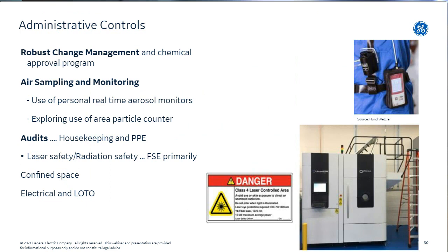Administrative controls that we can do are pretty much, I would say, on 3 areas that you can emphasize. First of all, have a good change management. That means when you're operating your machine and you want to change the material, or you have a new employee operating a machine, or you get a new machine, a larger one, and you have experience from the same manufacturer with a smaller system, do a good change management here. Understand where's the gap, what's needed to do the next step, what's needed to get the new employee being productive and working safe.